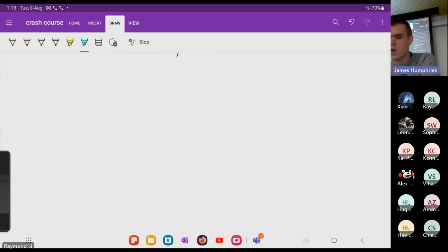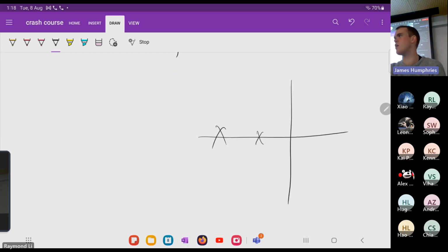But the main takeaway is if we think of our root locus, if I have a system that has, say, 2 poles here, what happens is as I increase the gain, they'll go together before they'll eventually split apart. But the problem is I may not want that sort of behavior. What I can do is put a 0 here, and then what's going to happen is as I increase the gain, this one will go away. What happens to this guy? The right one. The right one.